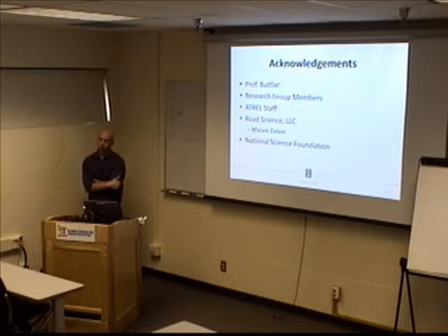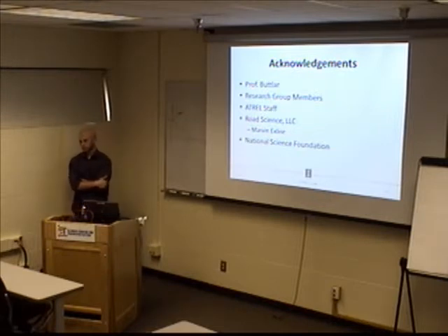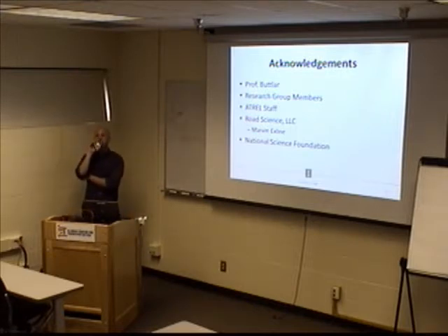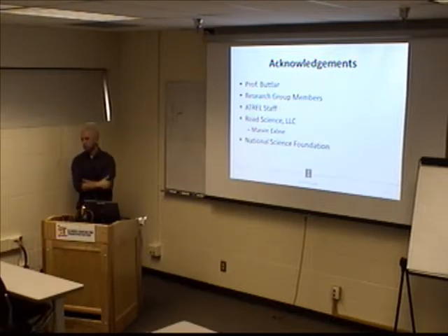The global fracture results are different, but we have a hard time getting insight just by looking at one clip gauge and one load trace. By focusing in on that full field, we can see how cracks are dispersed and branching, and what the mechanisms for energy absorption are. Why does it take so much energy to drive a crack through certain materials and not much energy through others? I think we'll know that a lot better.